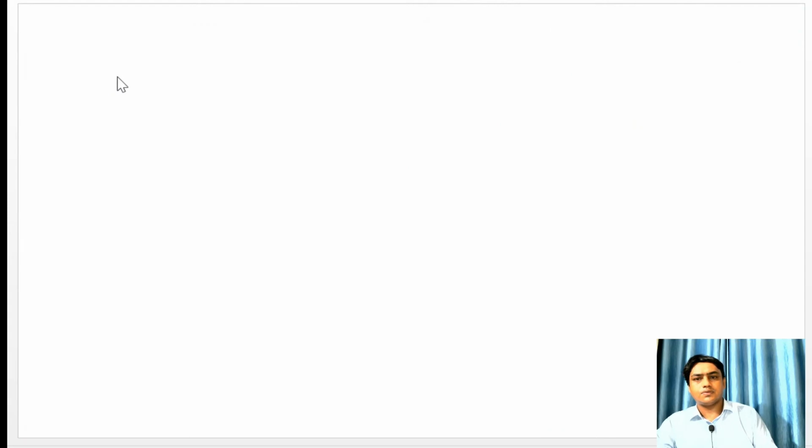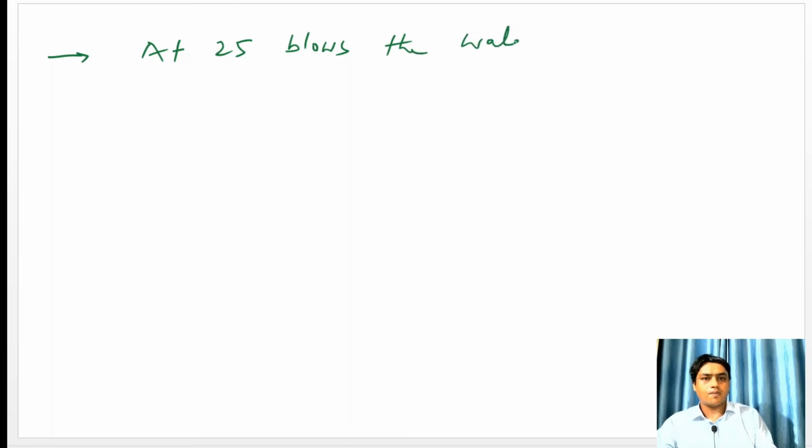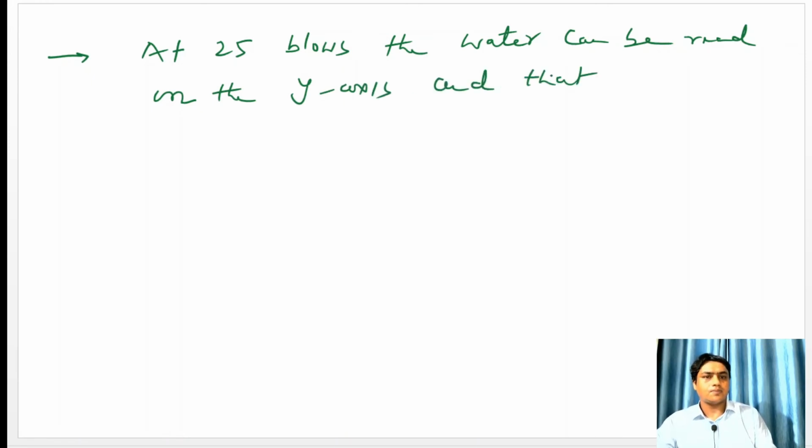So if you take 25 blows, the water content can be read on the y-axis, and that water content is called liquid limit.